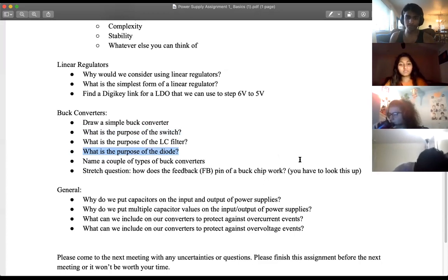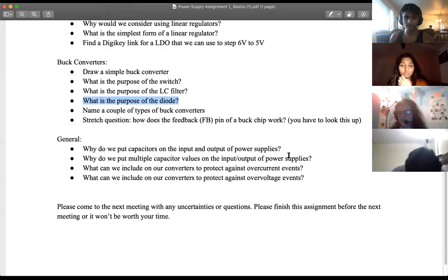So there's some voltage that, going back to inductors, I believe is caused by self-inductance. Basically, when you have the switch on, there's current flowing through the inductor, and that generates a magnetic field. And when you open the switch, because of the way voltage, current, and inductance are connected, you get a negative potential